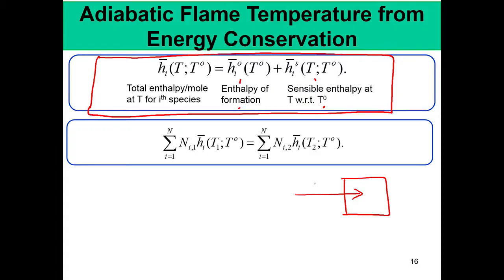So, please understand this, when you model combustion in a given engine, you cannot model it like an energy crossing the system boundaries. It is basically a rearrangement of the enthalpy from the heat of formation to the sensible enthalpy part. Okay. So, if there is no energy coming in, how do we model this? How do we write this?